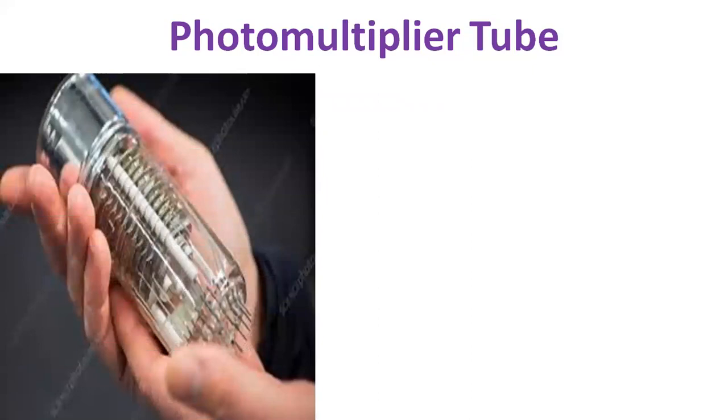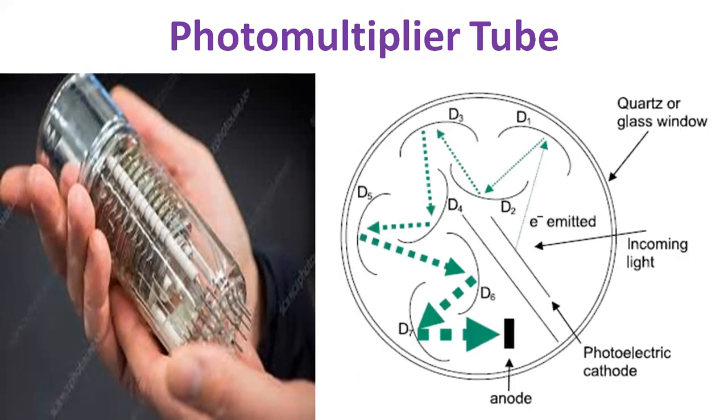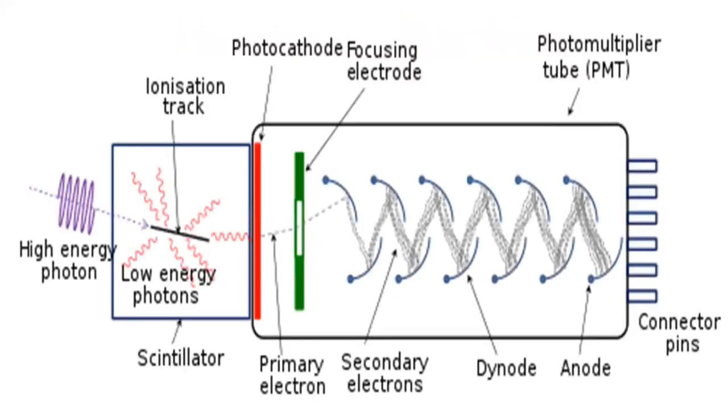Now, coming to photomultipliers, which are typically constructed with an evacuated glass housing using an extremely tight and durable glass-to-metal seal like other vacuum tubes, containing a photocathode, several dynodes, and an anode. Incident photons strike a photocathode material, which is usually a thin vapor-deposited conducting layer on the inside of the entry window of the device. Electrons are ejected from the surface as a consequence of the photoelectric effect.